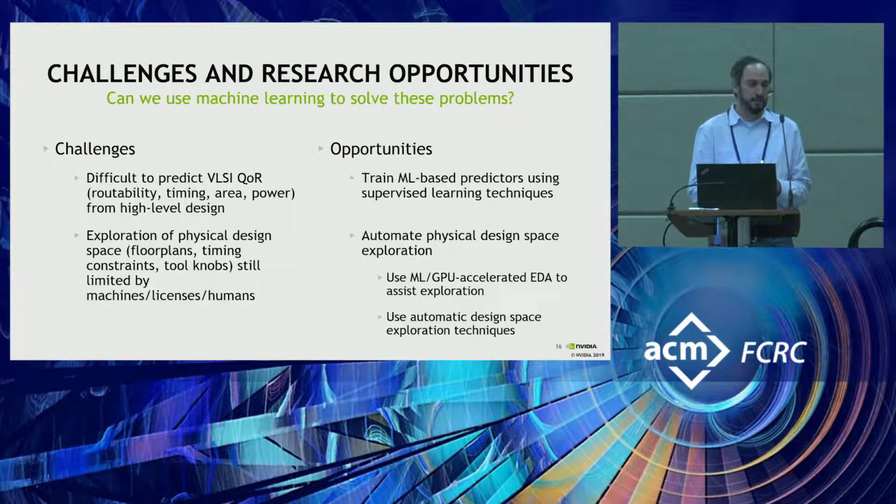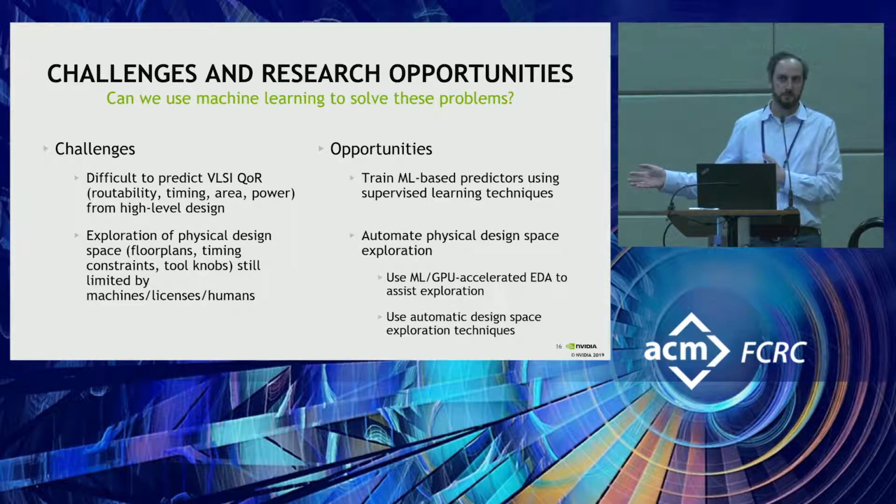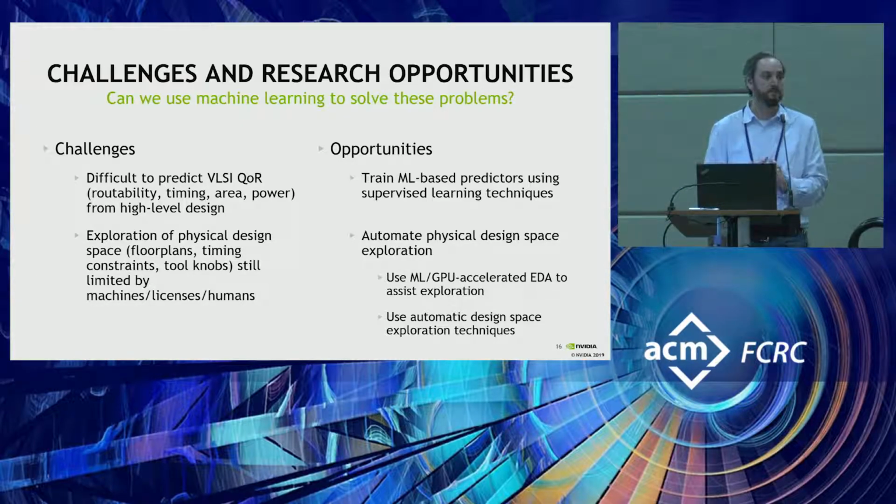And then there's a whole bunch of things related to maturity. One of the reasons HLS is nice is that all of our architecture simulators are built in C++. So if our goal is to have our synthesizable model very close to the architectural model, that's a big advantage.